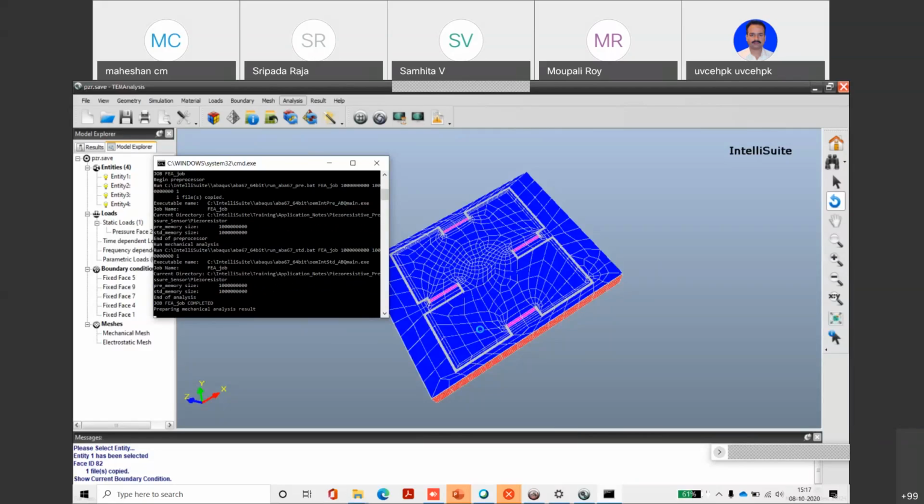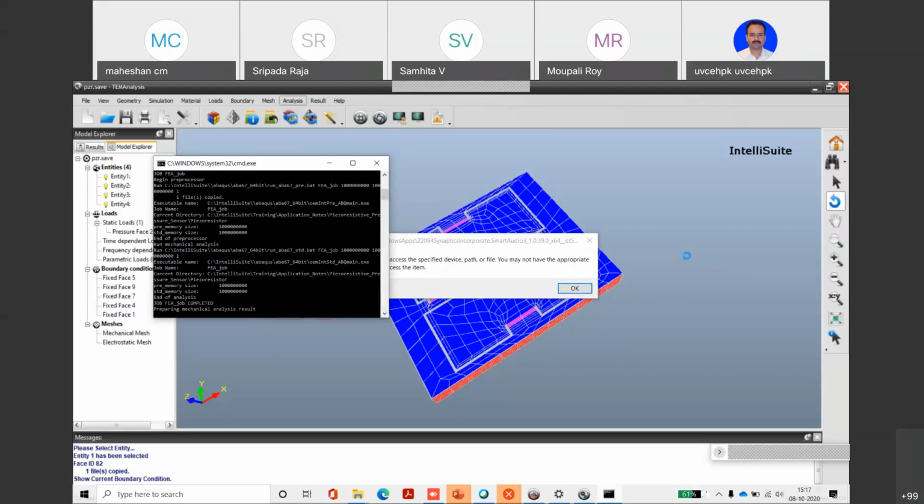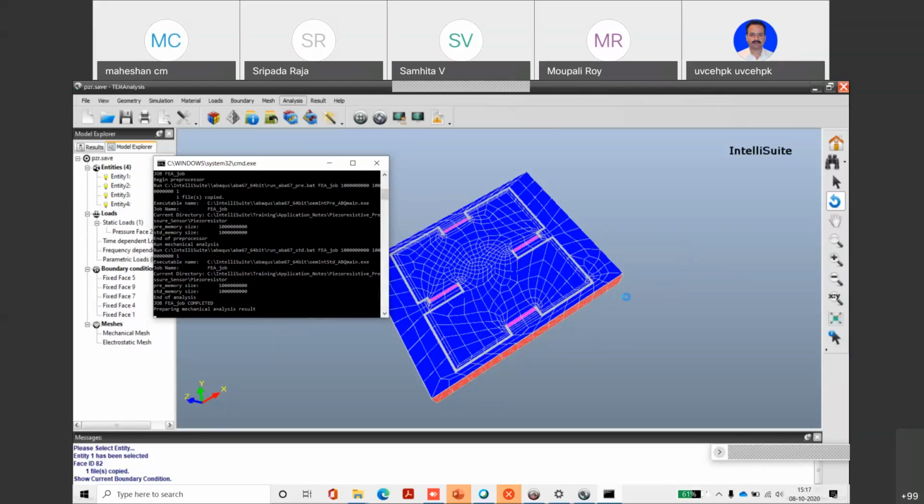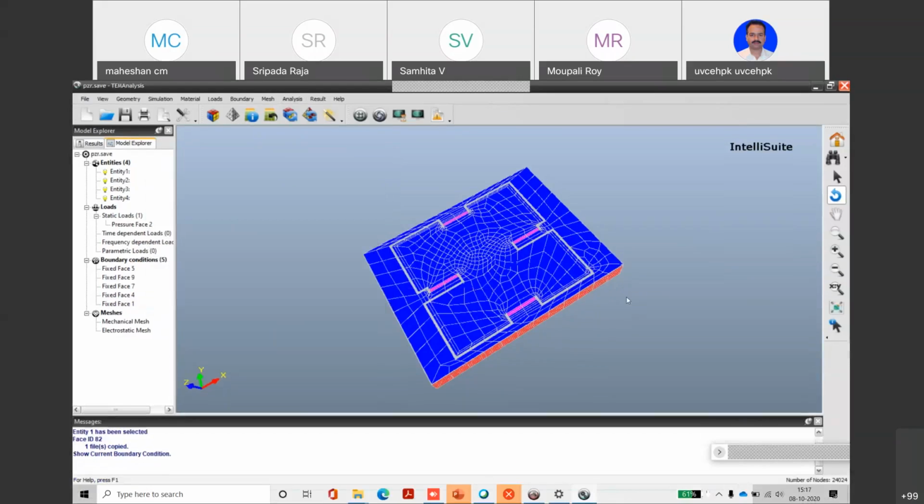Okay, if it takes only the resistors which are not connected by the wire, what should I do with resistors which are not connected by wire? So hence I will fool the software by saying that this wire is also a piezoresistor, but the pi coefficients are 0. Okay, so that's what I'm trying to do.